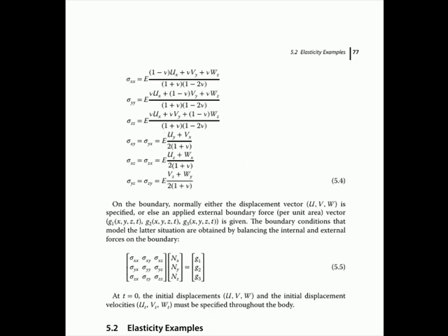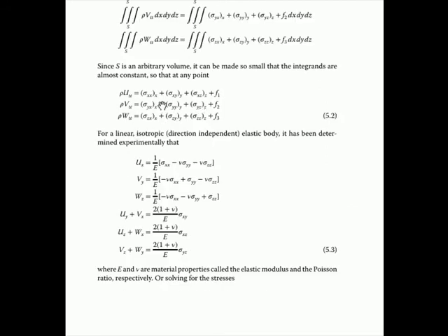So once you plug these formulas into the basic equation, here you actually have 3 second order equations involving derivatives of u, v, and w. Derivative with respect to time here, and derivative with respect to x, y, and z. Now, the steady state equations, you just replace the left-hand side by 0. In other words, if you run an elastic body out in time until things quit changing, until it reaches an equilibrium, then these will be 0, and those are the steady state elasticity equations.